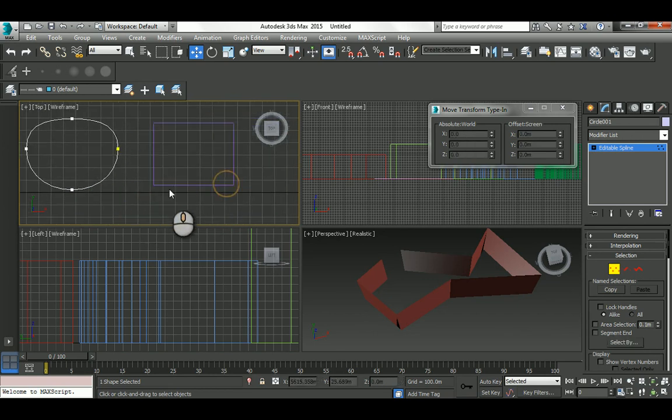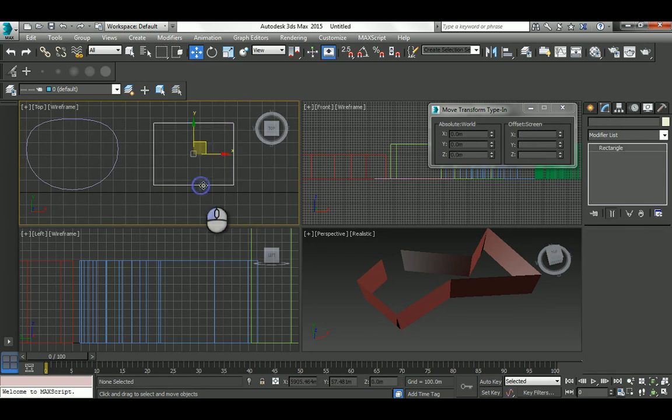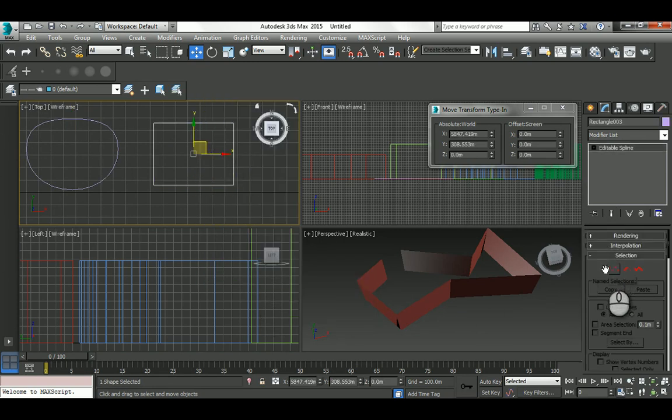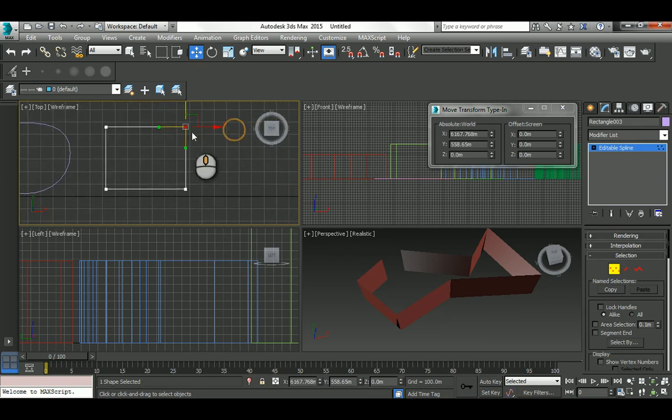This guy, turn it off first, and then select this guy, right click, convert to editable spline, and now you have points and you can distort it the way you like, to make different shapes, or select the segment itself, make it bigger and taller, but you don't have width and fillet corner now. You don't have the parameters that you have at the creation moment.